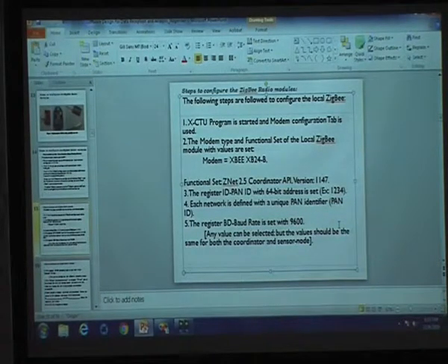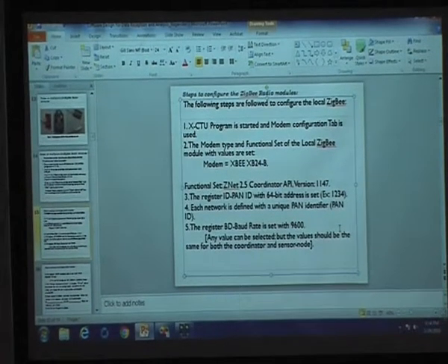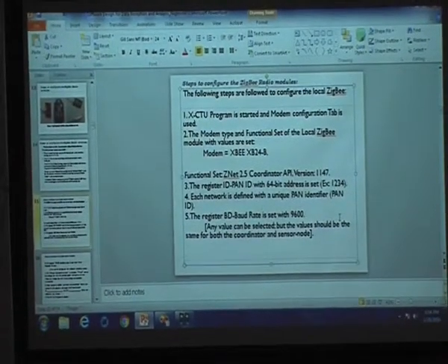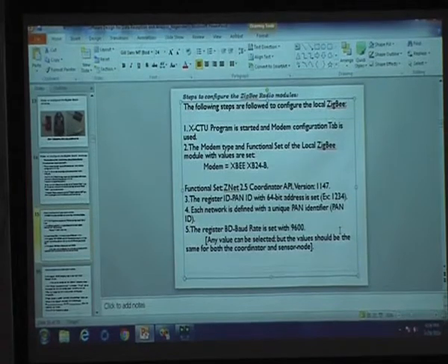So this must be synchronous. One more thing: the radio communication module and the hardware which is sending the data must both be synchronized to each other. If the radio communication module is at 9600 bits per second and your hardware data rate is around 115200, which is not compatible, they are not synchronized with each other. So the data rate of the hardware device and the radio communication module should be synchronized for appropriate data transmission to the receiving side. Make a note of this. By default, 9600 bits per second can be used here.